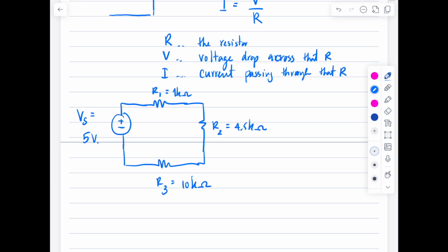As you can see, the current always comes out from the positive side of the voltage source. Let's call it IS. It's a good practice for you to analyze a circuit: when you have a circuit, you have to give a direction of the current flows, and then with that current flow direction, you give the voltage drop and polarity of the voltage drop onto each element.